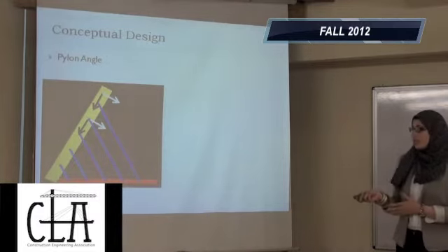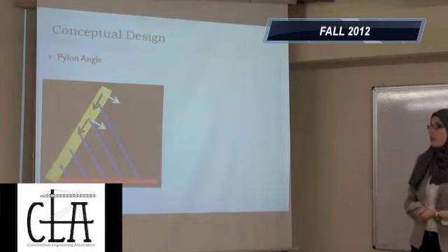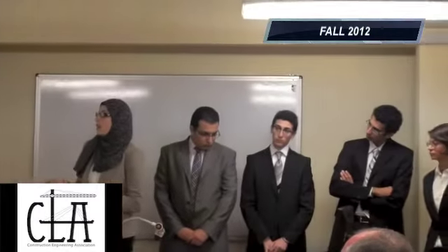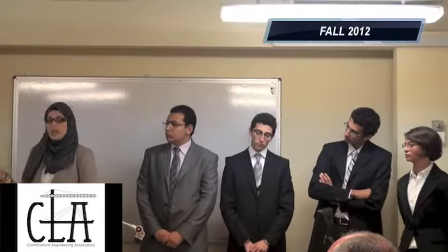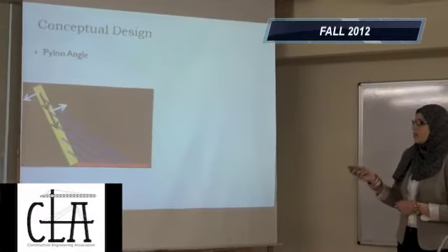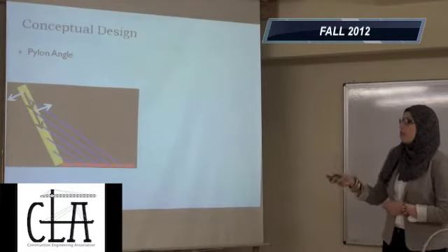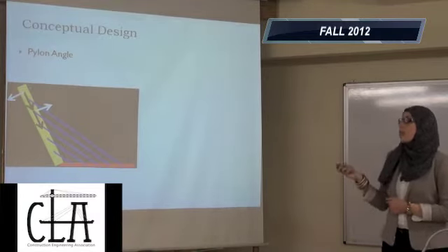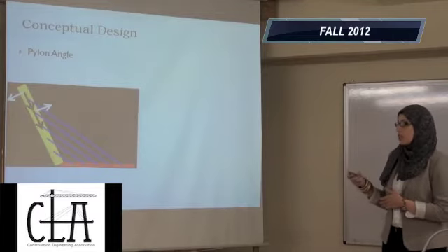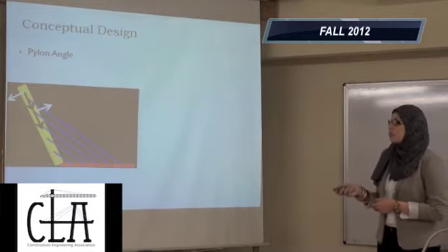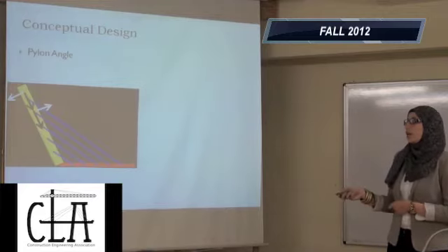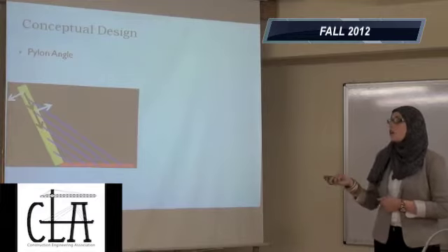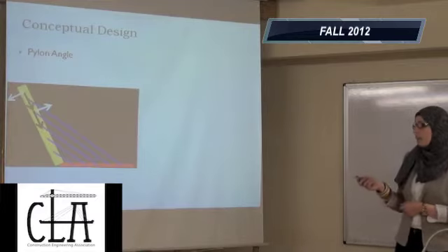And this structure is already unstable, so we will not consider it because to be stable, it will need the backstays, and backstays are out of our scope. The last case, which is our case, is when the piling is inclined outside. As we can see here, the two components will cancel each other, and we will have longer cables, and they will sag more, and it will require more tension, but the moment will be less. Actually, the moment produced at the base of the piling will counterbalance the weight of the deck. And we'll carry out a parametric study for the exact angle of the inclination.